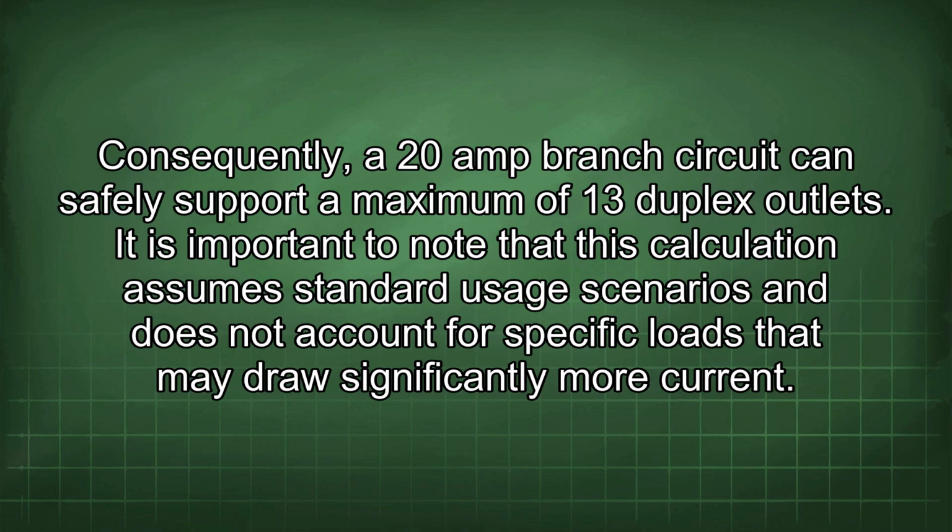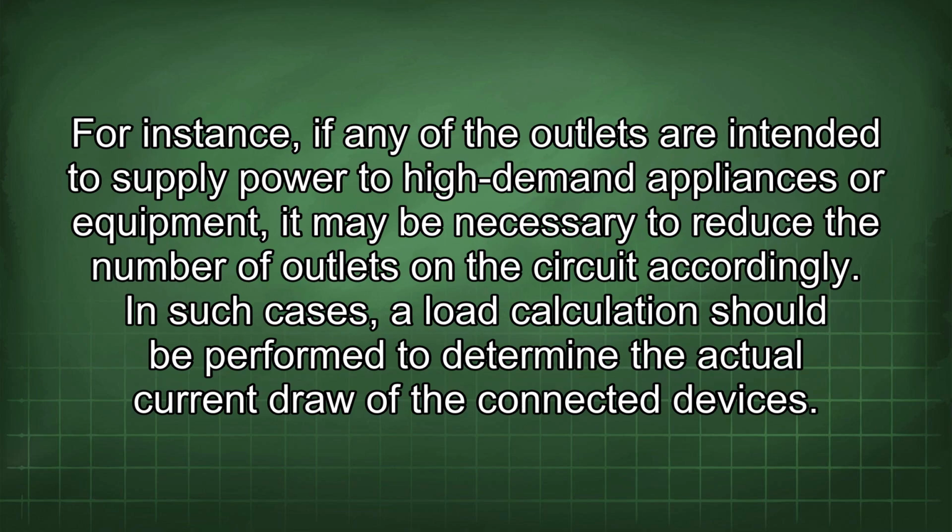It is important to note that this calculation assumes standard usage scenarios and does not account for specific loads that may draw significantly more current. For instance, if any of the outlets are intended to supply power to high-demand appliances or equipment, it may be necessary to reduce the number of outlets on the circuit accordingly. In such cases, a load calculation should be performed to determine the actual current draw of the connected devices.